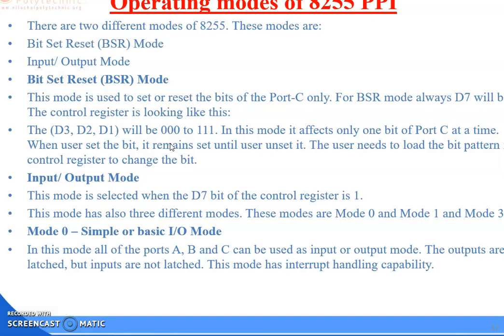When the user sets the bit, it remains set until the user unsets it. The user needs to load the bit pattern in the control register to change the bit. So next mode is input or output mode. This mode is selected